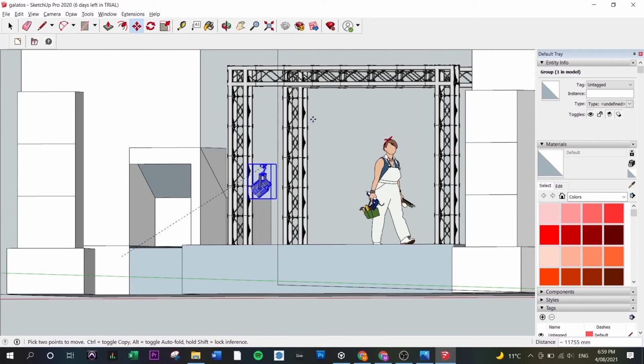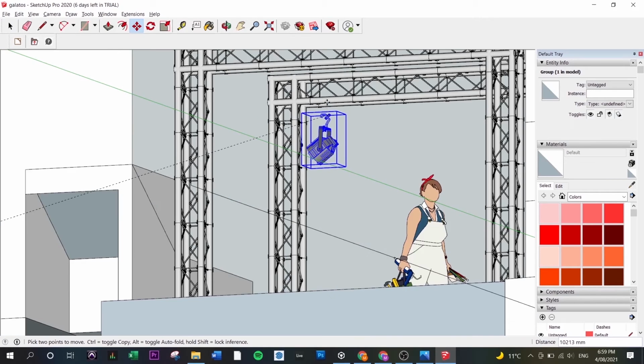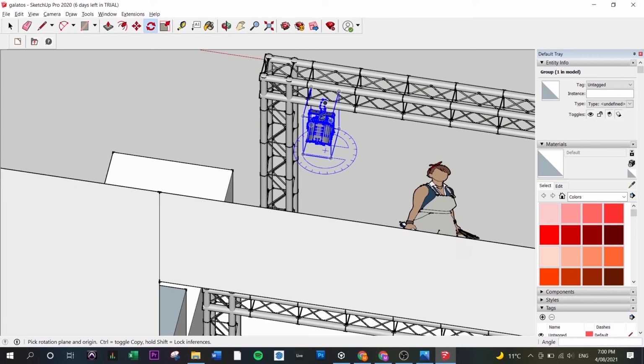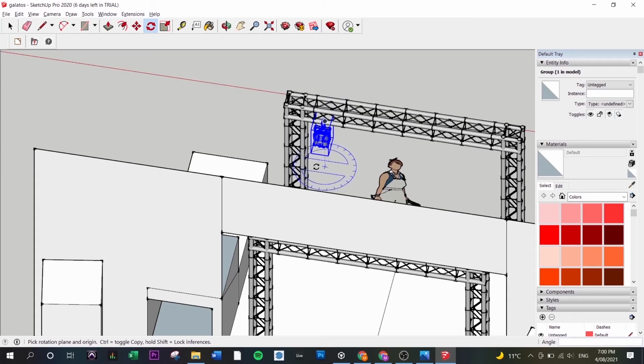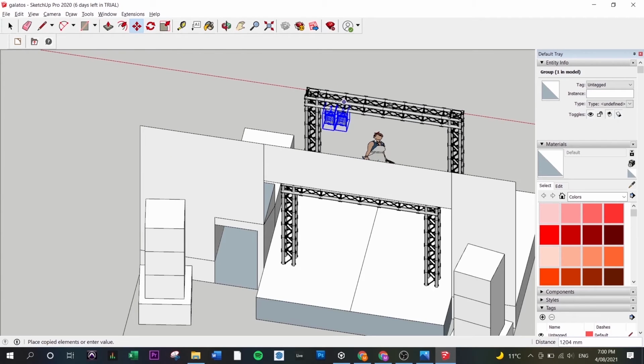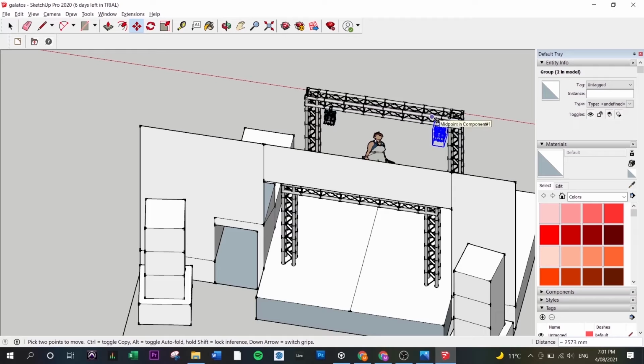So for this, for example, if we're placing it on that back truss, one tip if you want to space things out evenly: move it to the ends where the last fixture would be, and if you want there to be 5 within that gap, you just go divided by 5, and it'll fill that easily.